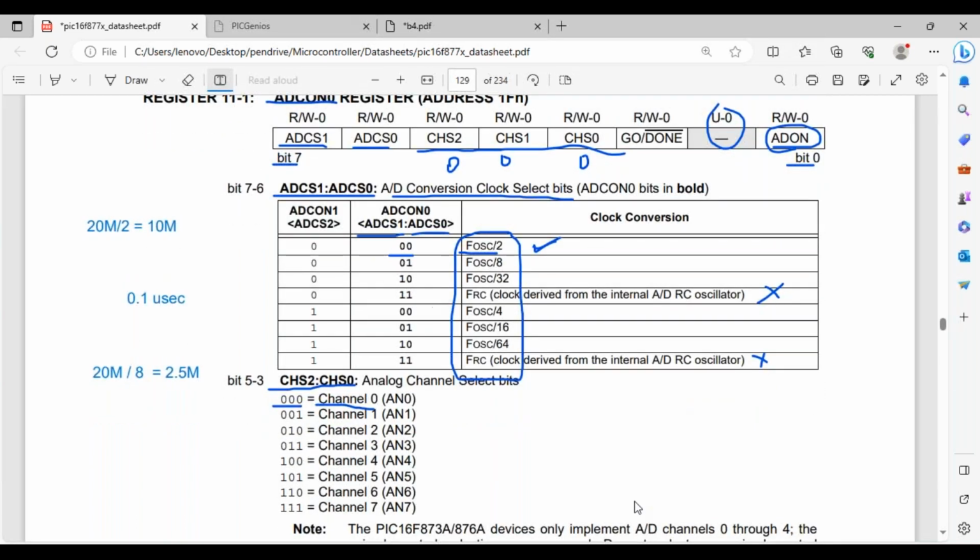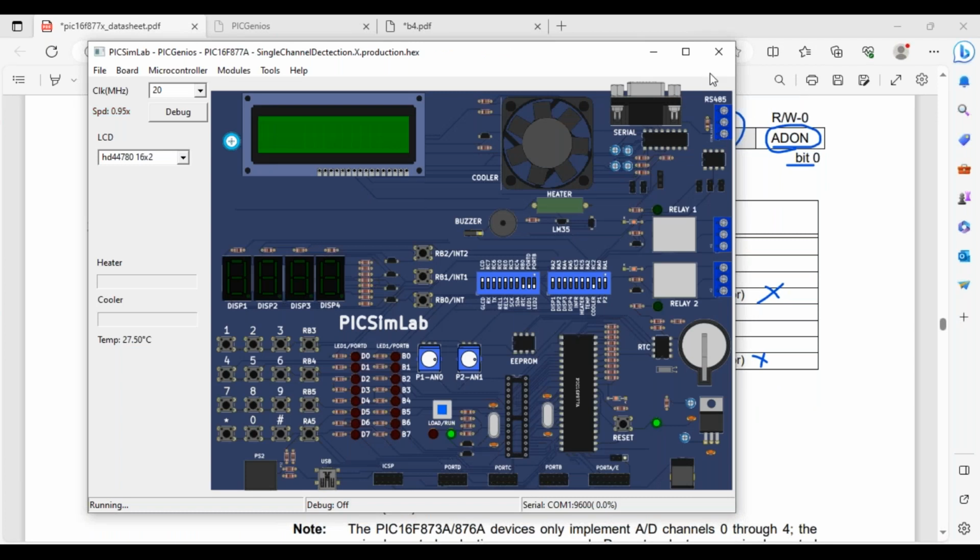Okay, fine. So you can observe the output here. I have configured the first potentiometer. To increase the voltage, you have to move it to the right. To decrease the voltage, you have to move it to the left. So I'm increasing the voltage as of now. I think it is lesser than 2.5 volts, which is why the digital value is lesser than 512. So the port D LED is not turned on. Oh, sorry, the DIP was in the opposite direction. So it is greater than 512 right now, and because of that, the LED is turned on.